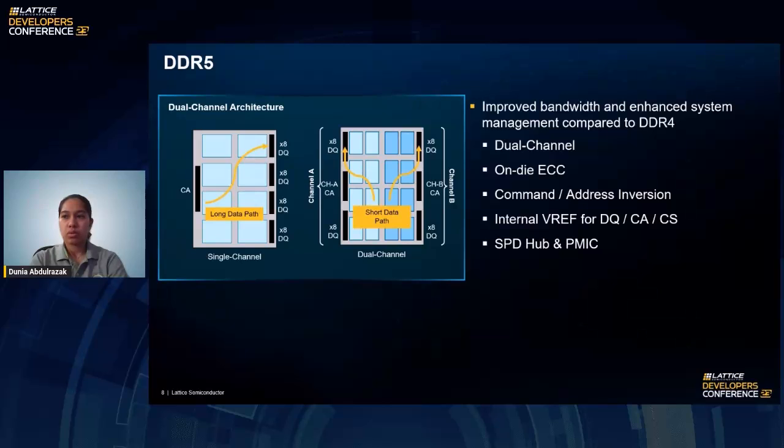DDR5 also introduces on-die ECC to ensure data integrity and command address inversion to improve reliability. DDR5 also supports internal VREF not only for data signals, but also command, address, and control signals.